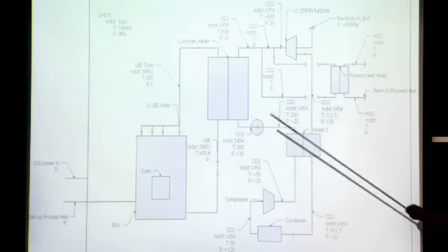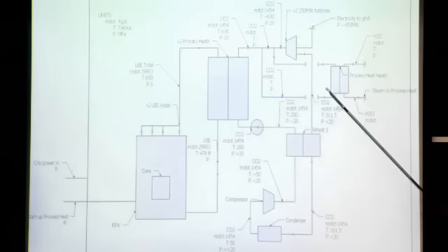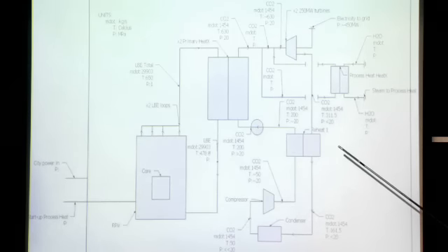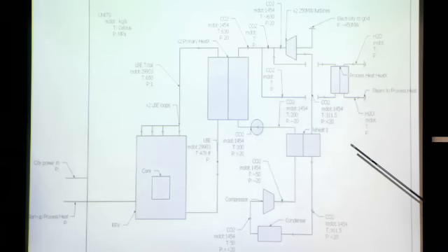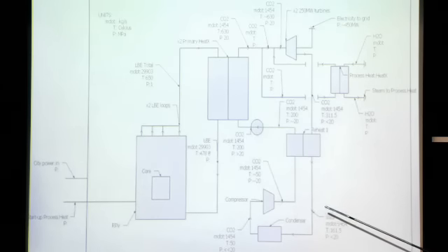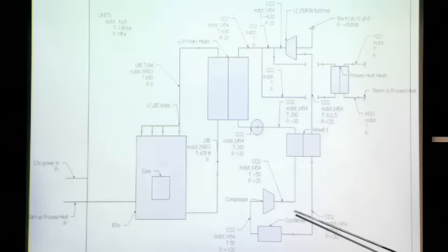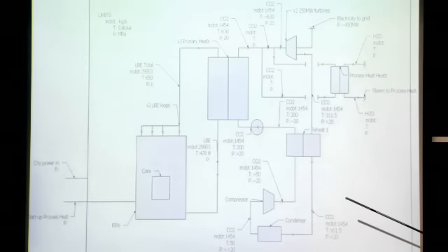With our initial calculations of temperature drops, we were able to get some values and some generic pressure ranges that we're going to use going forward to keep the CO2 supercritical and make sure that nothing is too out of the ordinary. And we were able to calculate a mass flow for ocean water or river water for the condenser, and that was well within reason, which is a good sign moving forward. We'll be able to be successful in our optimization.